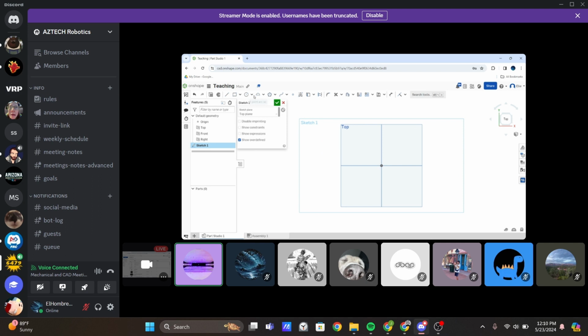On these planes, you draw shapes, basically. Here you have different rectangles, circles, arcs. So if we were to make a cube, you can start with a center point rectangle. You click where you want the center to be, and then you just drag it out and click again. And then to dimension it, there's a dimensioning tool, and you can just make each side a certain length. Also, make sure that your workspace, I can't remember exactly where it is, I think when you initially set up your account, make sure that you are in imperial units, not metric.